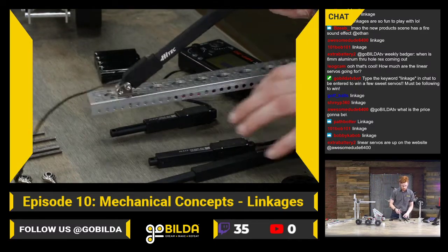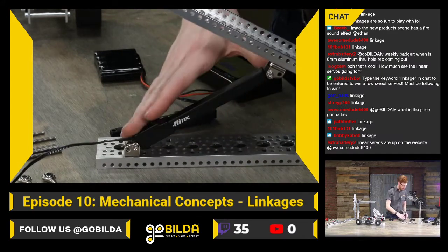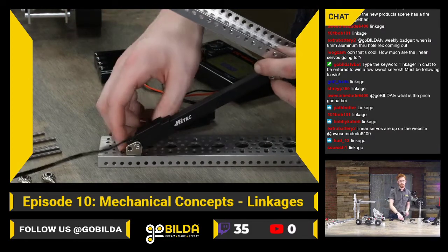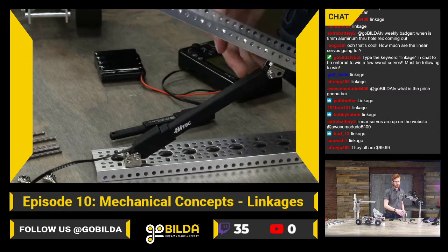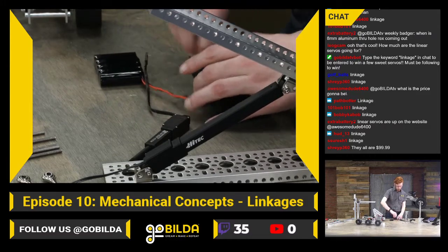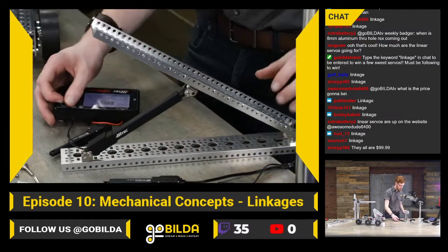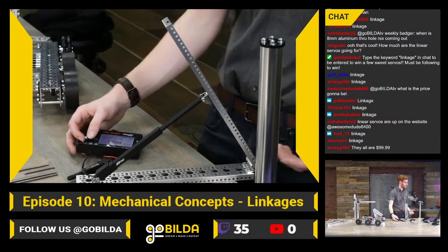So this is a piece of channel, and a nice thing about the linear servos is that they come with some nice steel mounting brackets that are the goBILDA pattern. So they have M4 holes on an 8mm spacing, and they work out really well with goBILDA stuff. So I will plug this bad boy in and see how it runs. This is, I'm going to say, the most common use case for a linear servo, or a linear actuator for that matter, if you're looking at an outside of FTC application.